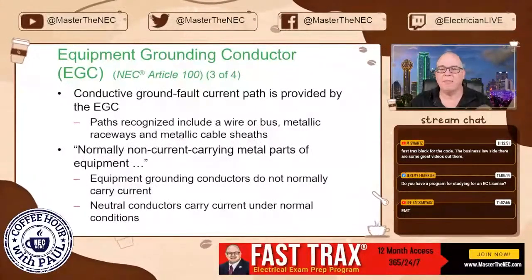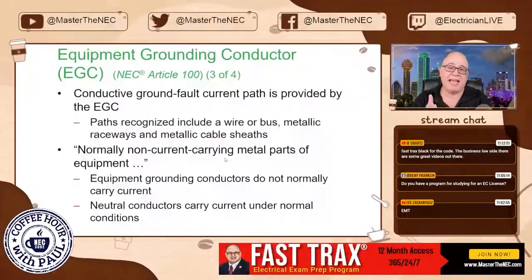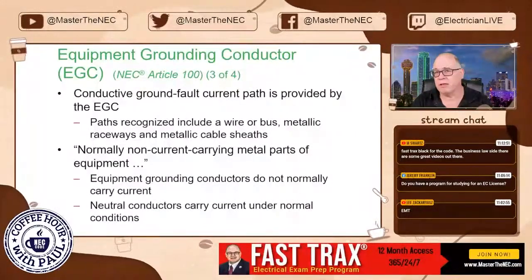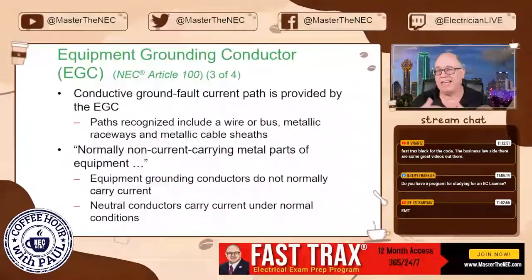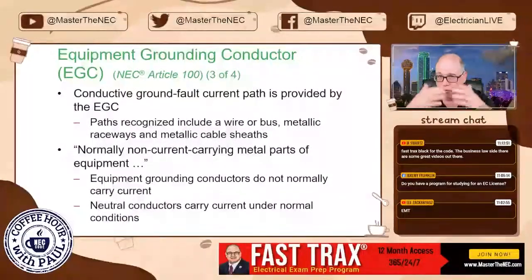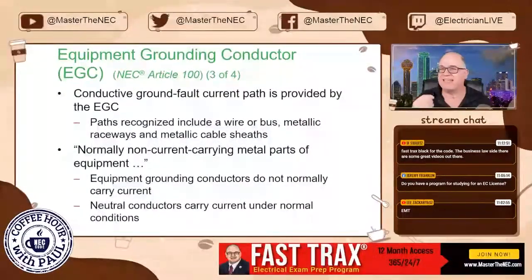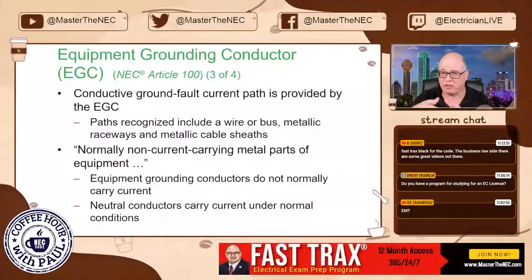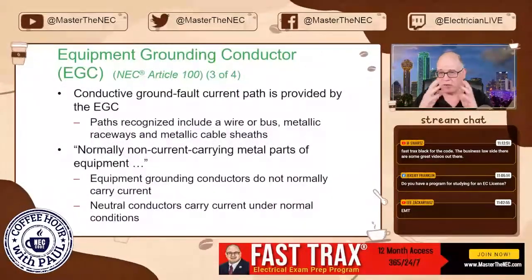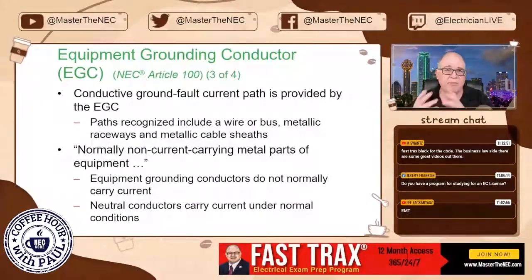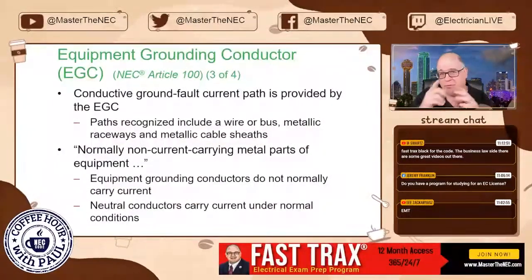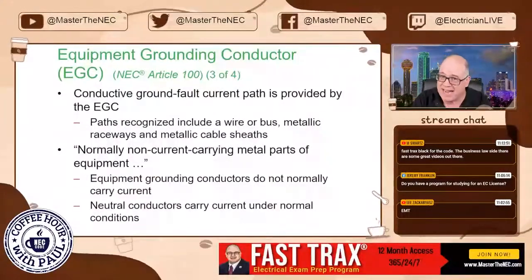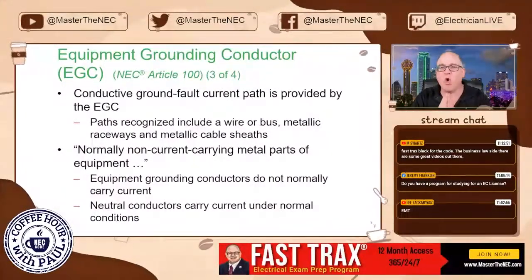And then the metal sheathing is the case with AC cable, for example. With MC cable, you don't use the metal sheathing as an equipment grounding conductor unless you're using something like a smart ground product, which was specifically designed for that. And it doesn't get any larger; you can't go past 6-gauge conductors. That's where an MC actually acts like an AC cable, where you can use the armor. But that only applies on a specialty-made type of MC, not normal MC.